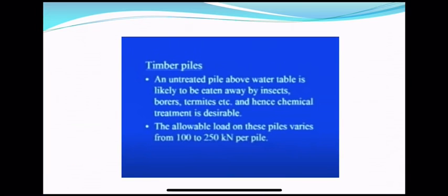Usually when we are going for construction, it will be our decision which type of pile, what the length should be, and what the diameter should be. So if you know the properties of typical piles of different types, you can make your choice easily depending on the conditions at the site. You can pick timber piles if the load is lesser and if there is no water table present.